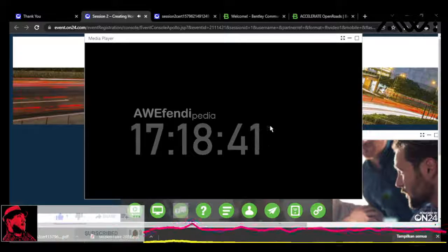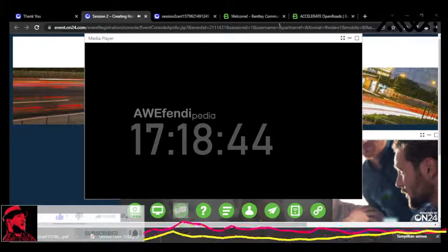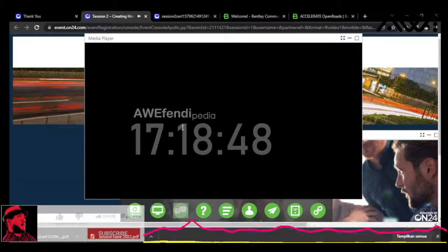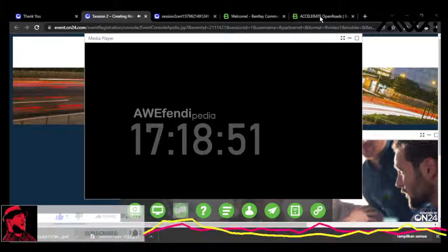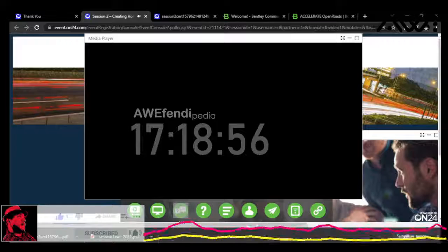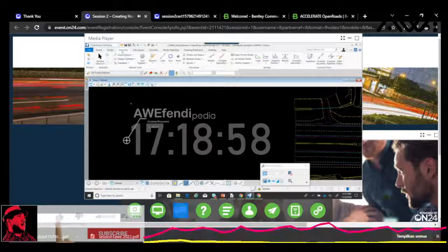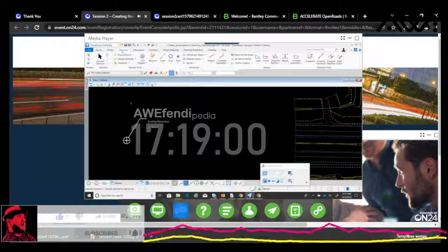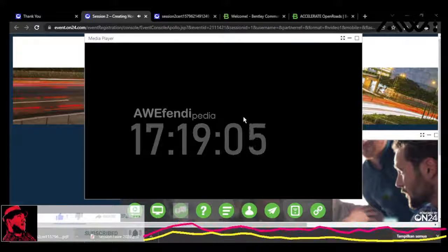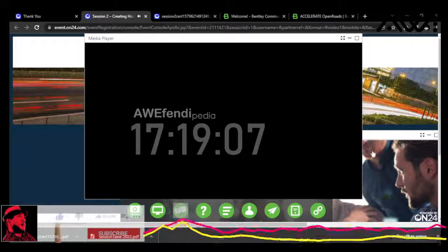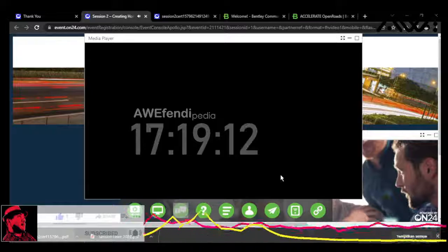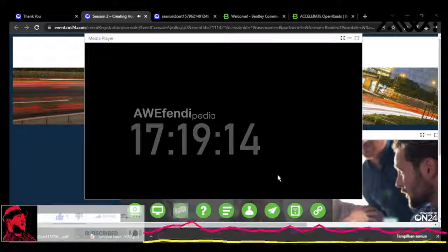Now, I'm going to start, and I'm going to lay this out first of all graphically. So I'm going to go to the OpenRoads Modeling workflow, go over to the Geometry tab, and I'm going to lay this out graphically by elements, meaning I'm going to draw tangents, I'm going to draw arcs, and so forth, and then put them all together in an alignment, adhering to that known bearing, distance, curve radius, curve length, and so forth. So to begin, again, we're on the Geometry tab. We'll get on this area under the Geometry Tools, and we're going to begin by just placing a line.